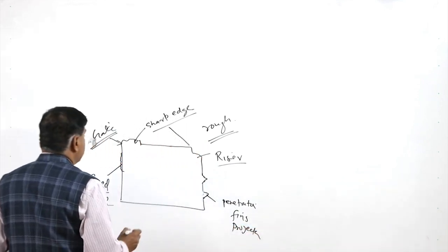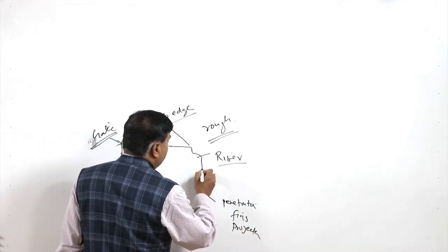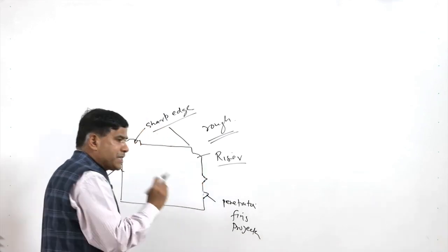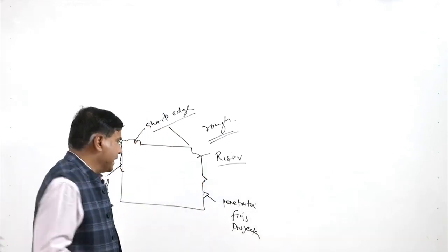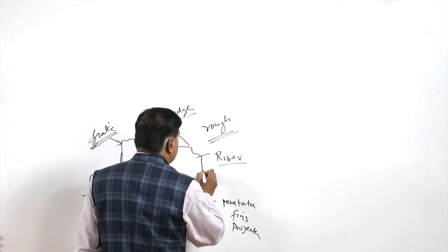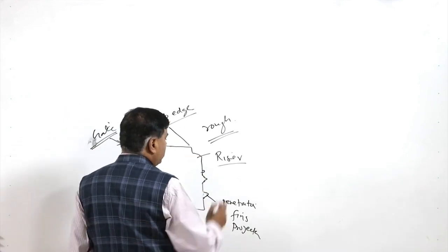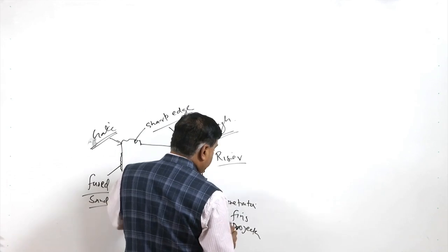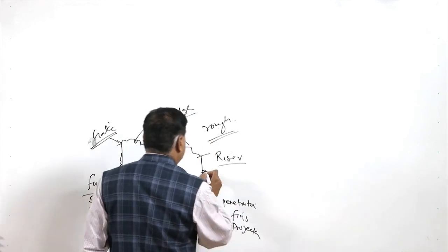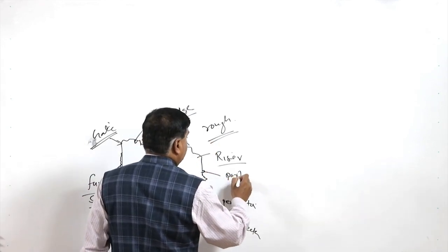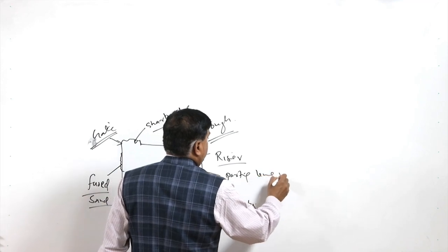These projections may also be present at the parting lines in form of additional metal deposited at the parting line. So, parting line metal may also be running along the length of the casting at the parting line. So, these need to be removed. So, parting line metals.